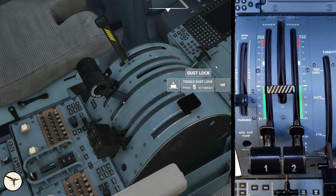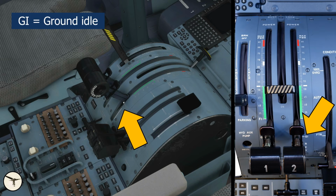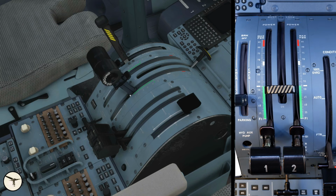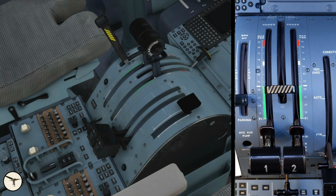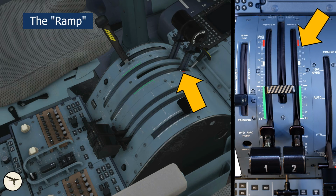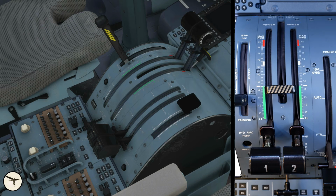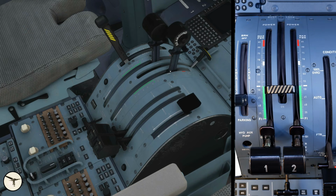This is the gust lock. When it is engaged, it prevents power from being increased for takeoff. The power levers have some positions you must be aware of. This is full reverse, ground idle, flight idle, the notch, which is the position from takeoff to descent, the ramp, which gives 100% power, and the wall, which gives emergency power, 115% torque.